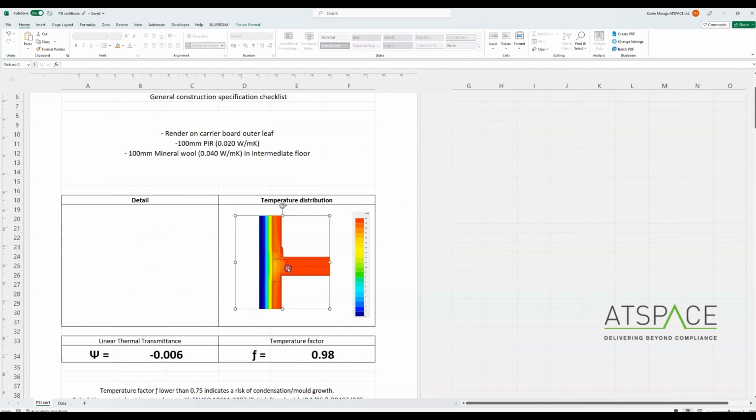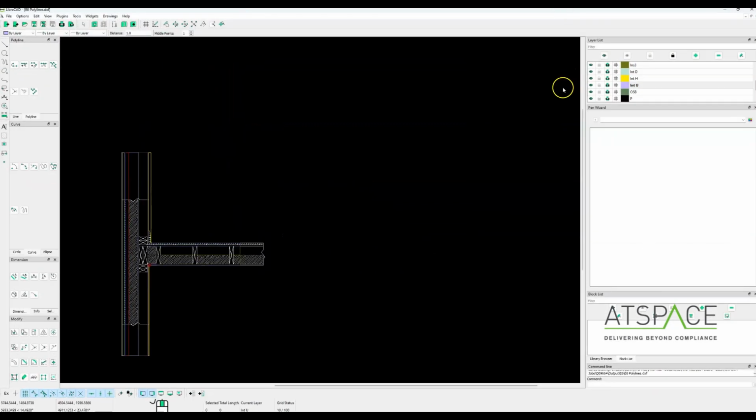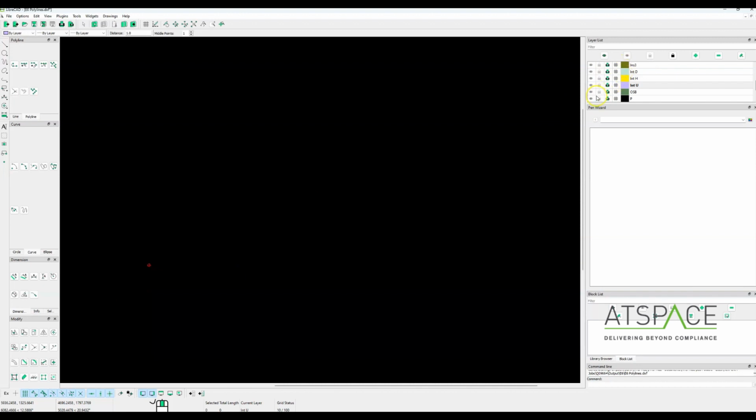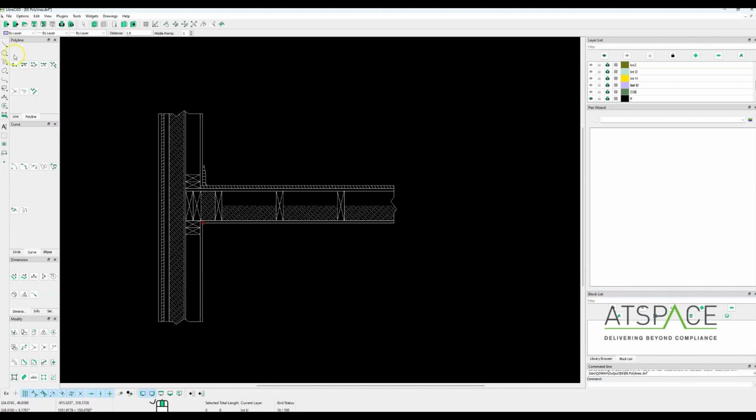Now we could use the original drawing provided to us by the client for the other side where it says detail. I prefer if we get the polylines because we've tidied these up already. So if we click here, that will hide all layers, and then we'll just view the original P layer there, which gives us a nice visual detail.